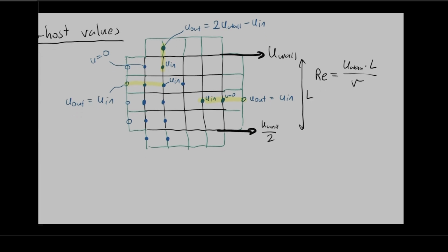Okay. All right, so let's talk about the vertical velocities. There's going to be a few fewer of these because they're very similar to u velocities. Where are they stored? Well, the vertical velocities are stored at these locations here. So, for example, I know here that v is equal to 0 because I cannot go through that vertical wall. No fluid can go past it. And so if this is my v in, then my v out is going to be equal to v in. This is now an even function of y. And so those are the values that get linked together.